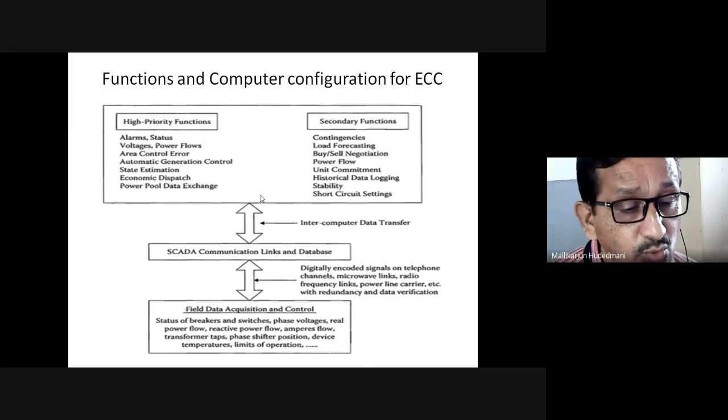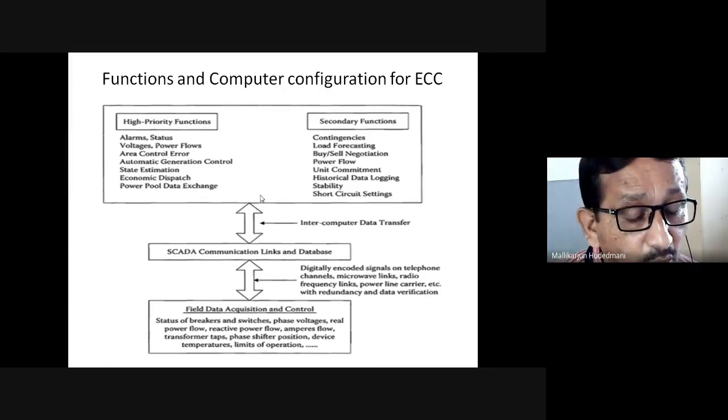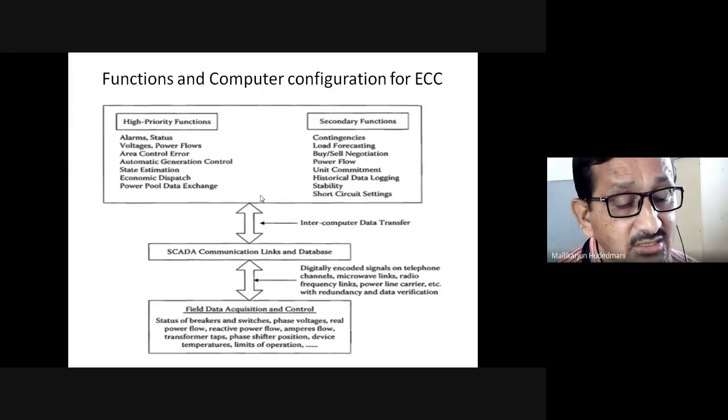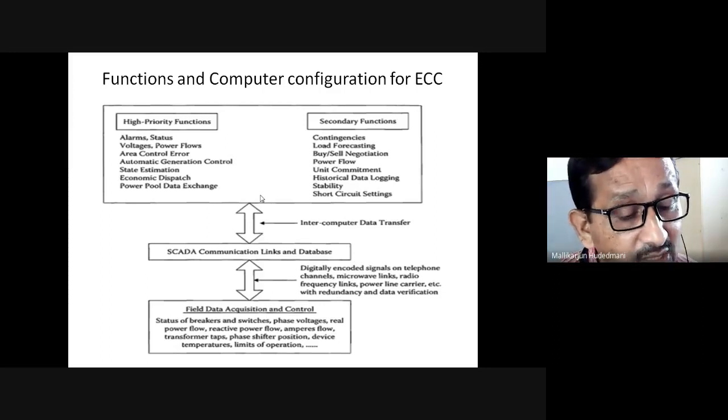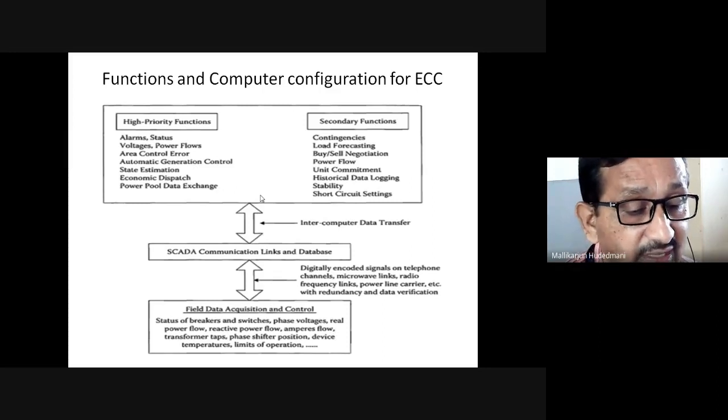What is the change due to load variation? That error has to be zero. If error exists, it means there is a deficit generation noticed on that station. The generator has to cope up that generation and make the error zero. That is the indication on the generator.